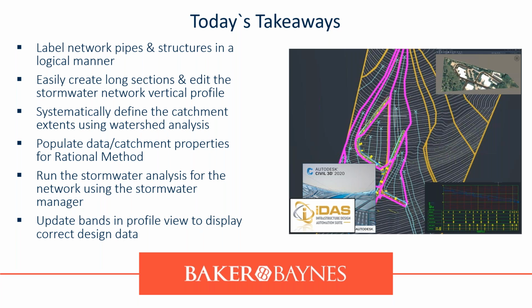We use the watershed analysis, we use the water drop, which is brilliant to help us understand what's going to be contributing, so that we don't create an overly conservative design and we do not create an over-contributing catchment. Okay. Sometimes it could be in your favor, sometimes not, but this is very streamlined and much more to the point and precise. Thereafter, we inputted the data for the rational method.